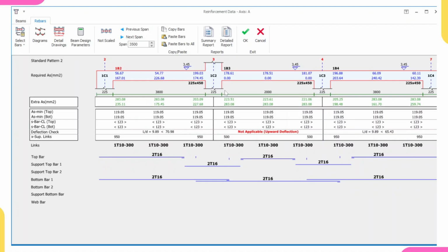And also, assuming higher load was coming to this structure, something like a commercial building, you see now here will be something like 3y16, and this, if you do not hinge it, will be having that kind of 3y16. So that's why I say hinge your beams. Make sure you hinge it to save cost, to reduce the moment coming on it. Because assuming we do not hinge it, here will be something like this, 119. So that's the advantage of hinging your member.